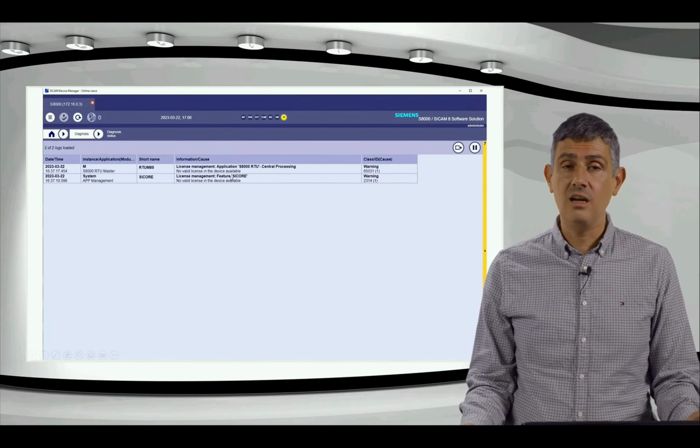We do the same for the alarm list. So new picture, alarm list total as name, only alarms, confirm. Then click here, select alarm list total, and done.